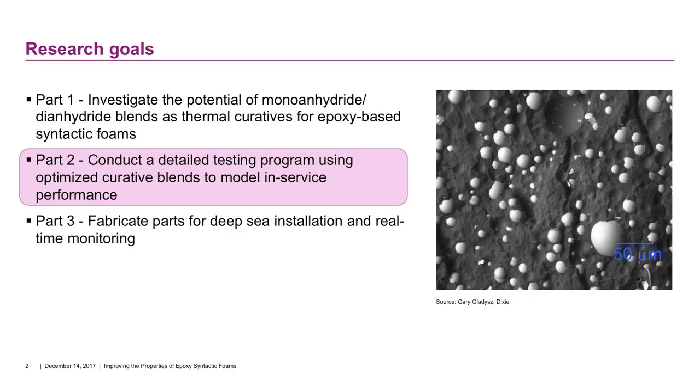So let's take a look at the overall goals of the research study, where we've been and where we want to go today and in future. In Part 1, what we focused on is just what the potential would be for combining different thermal curatives, in this particular case monoanhydrides and dianhydrides, and what influence they would have on the properties of the epoxy syntactic foams. And we started to find some very interesting results, particularly with regards to glass transition temperature and compressive strength.